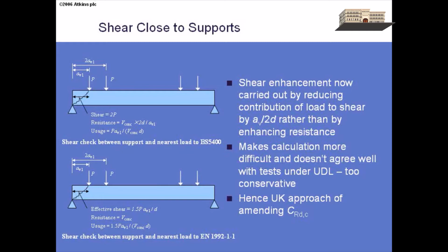And the other real danger is if you start reducing loads to calculate your shear, if you actually do that in the computer model, then there's a real danger that when you come to design your substructure and your columns, you've actually got artificially reduced loads. So that they've just been reduced solely for a fudge for shear. So there are lots and lots of dangers.